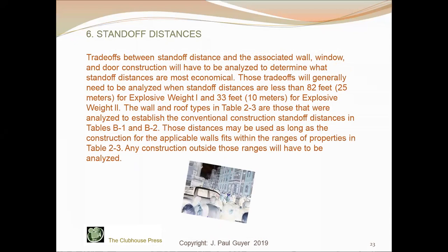So greater standoff distance, in other words, preventing vehicles and people from getting close to a building or buildings, comparing the benefits of a greater standoff distance with the reality that perhaps you cannot control a great standoff distance, and so you have to construct walls, windows, and doors to have greater blast resistance.